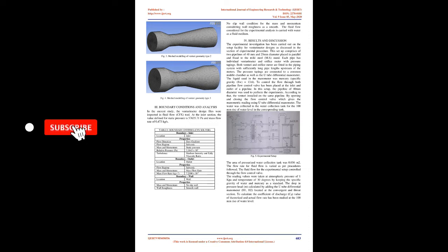Is the density of the liquid on the upstream location 4, 5. The discharge coefficient, CD, is a ratio of actual flow with the theoretical flow. The purpose of this study is to introduce the effect of the discharge coefficient, CD, on fluid flow measurements using a Venturi tube. However, to account for real fluid effects such as viscosity and compressibility to the empirical coefficients, CD